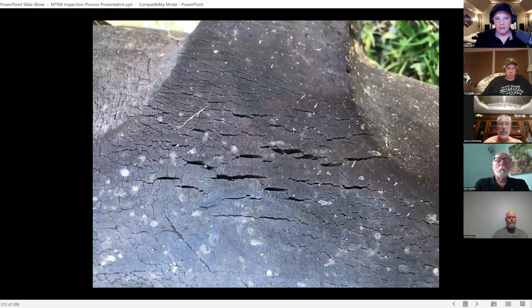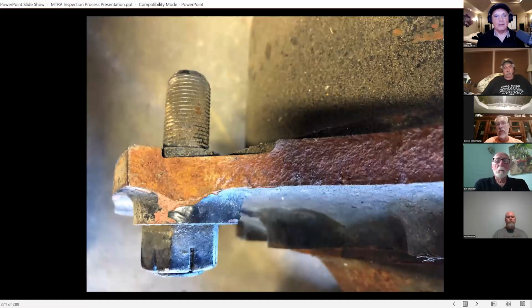Something else, I kind of hate to mention it. As you're walking around the pits and guys are tiring up, I've noticed lately, with all the bigger impacts that are being made, some guys just really hammer their studs when they're putting the wheels on, and you can over torque them and stretch the threads and ruin them by that alone.